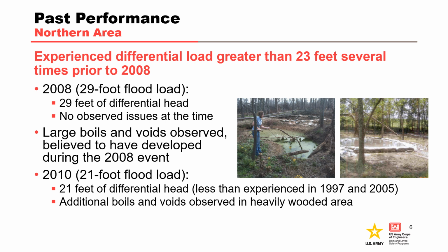Later in 2010, the levee was exposed to a flood load of approximately 21 feet, which is 8 feet less than the 2008 event and less differential loading than had been experienced several times prior to 1997 and 2005. During this event, levee operations personnel observed more boils and voids on the land side of the embankment in a heavily wooded area. The progression of poor performance at lower differential head indicates that an erosional process had likely been initiated.